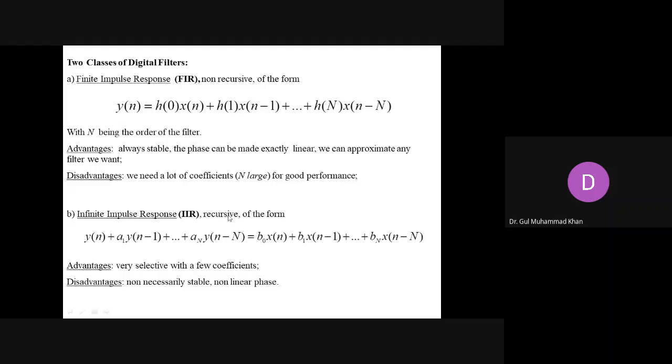In comparison to this, we will be discussing the second type of filter, infinite impulse response filters, which are feedback systems. They, on the other hand, have this advantage that with just second or third order, they give a response equivalent to 100 order of FIR. So that means less computation. But then they have this disadvantage of getting unstable as well at some point.